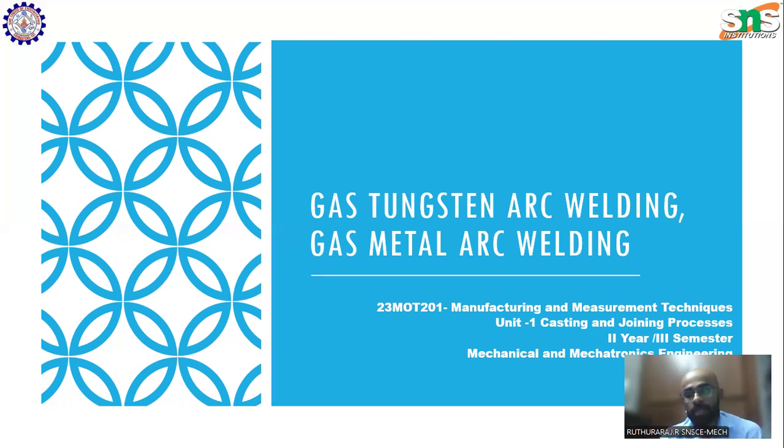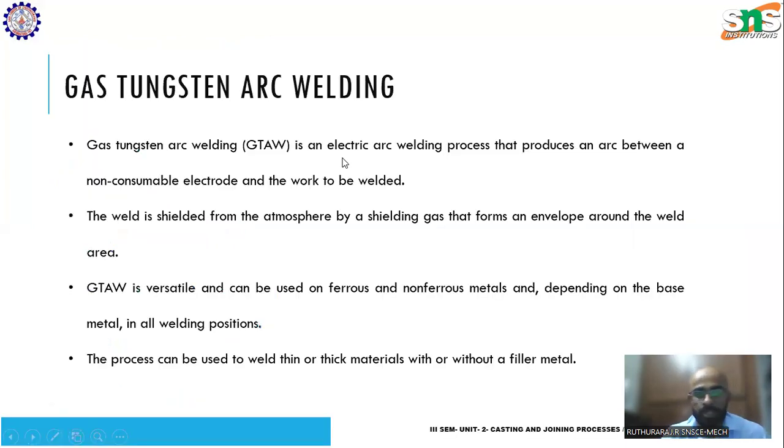If you need to weld thick plates or use it for a longer duration, then it may not be sufficient. In such cases, these advanced processes are used. Also, the shielding is not proper when used for longer durations, hence we go for the advanced process. Examples for gas tungsten and gas metal arc welding are robotic welding and welding of automobile bodies. Any industrial component can be welded using these welding processes.